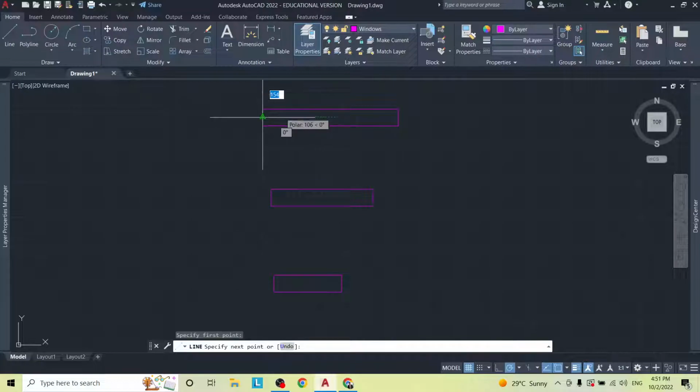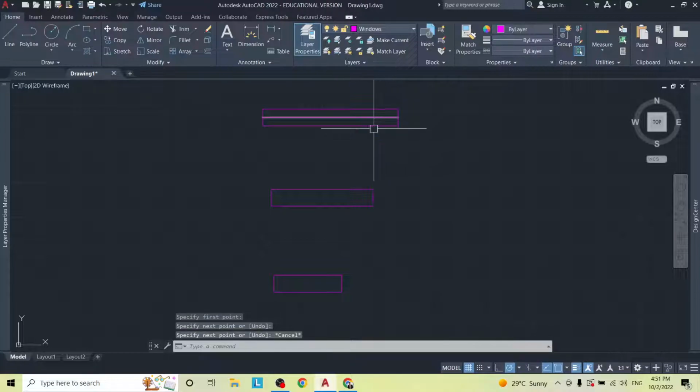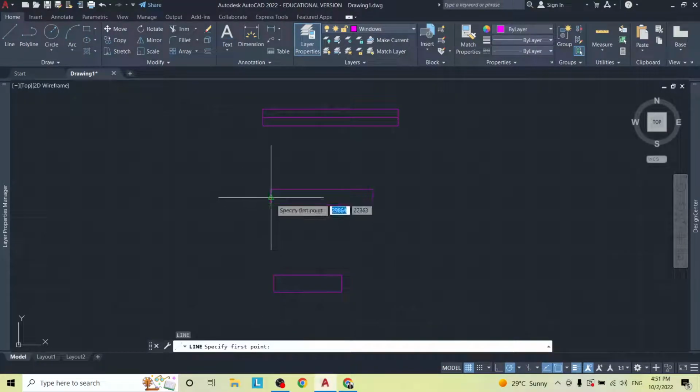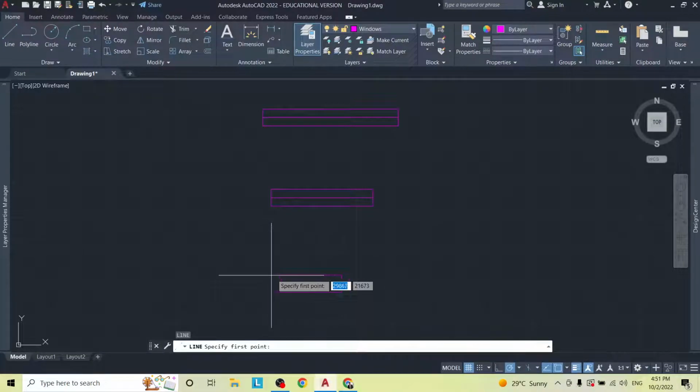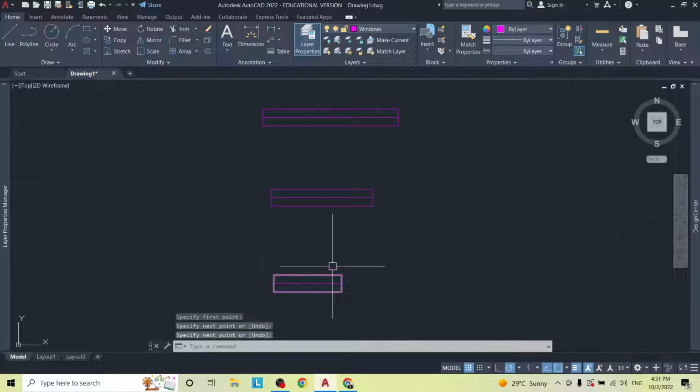So from here, you notice that triangle show up because I have on my midpoint snap. Use a line tool again. I just hit enter to reactivate my line tool. If I last used my line tool, I could just hit enter and it's going to reactivate the tool that I had last. That's a little shortcut. And hit enter to end it rather than escape. Enter again to start it, line tool, enter again to end it.